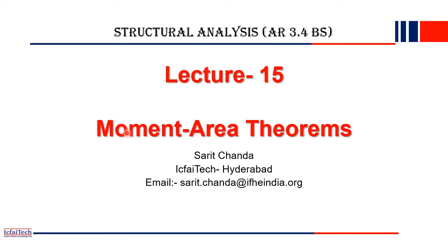With all the methods we can calculate the slope and deflection, but each method has some advantages and disadvantages. Some methods may be useful in a particular condition. For another loading condition, if you use the same method, it may be troublesome, and you may have to use another method. So in this course we'll see four types of methods to calculate the deflection and slope. In the last class we discussed the double integration method. This class we'll discuss the moment area method. In the next class we'll discuss another method to calculate the deflection and slope. Essentially all the methods calculate the slope and deflection of a structure.